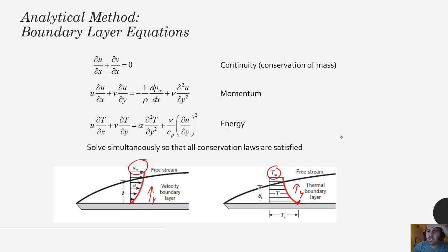So we've treated convection, if you remember, Newton's law of cooling is the flux equals h times delta T, and the delta T, again, we're looking at is from the surface temperature up here. And we've treated that as just a sudden change in temperature, just a sudden temperature drop. But as you can see from the plot here, there's actually more of a gradual change that's happening. And this boundary layer basically describes what's happening in terms of temperature when you're very close to the plate.